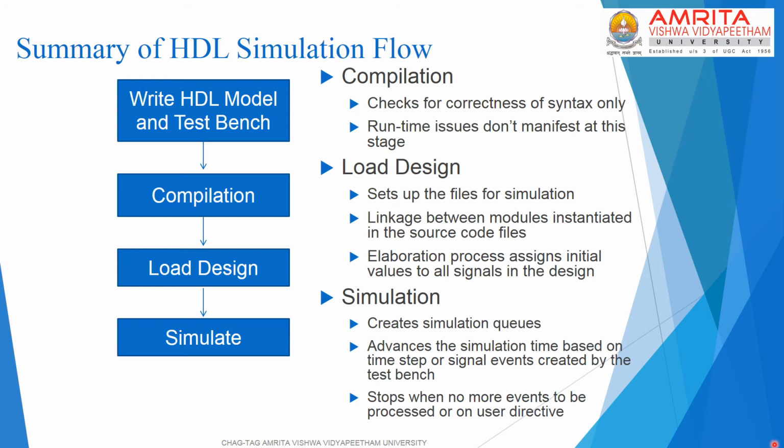The next phase is called the load design phase, where the design is loaded into memory for simulation. Now in this phase, the linkage between different modules has to be correct. If a particular DUT is instantiated in a test bench, then all the input and output ports of the DUT have to be properly mapped onto signals in the test bench. This will be illustrated in the example that follows.